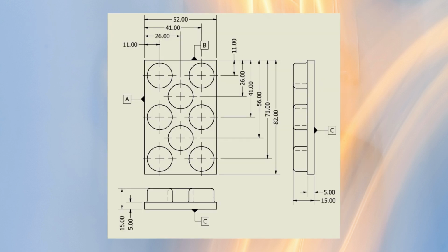Here we can see a three-dimensional model. Only the lengths have been dimensioned, as in this drawing these are the only areas controlled by the datum. That is, these datums control dimensions only, and are not related to any surface. As the model is three-dimensional, there are three datums. In each plane there is a datum and all measurements are taken from one of the marked datums.